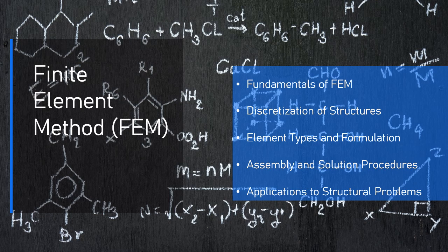For a 2D plane stress element, each node has two DOFs, displacements in the x and y directions. For 3D solid elements, each node has three DOFs, displacements along x, y, and z directions. The global DOF corresponds to all the displacements, or rotations, at the nodes in the entire structure. 2. Global stiffness matrix.